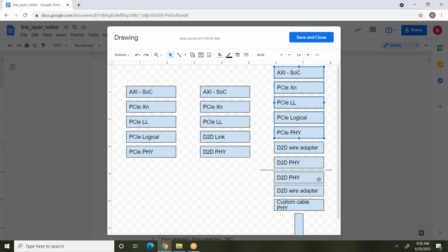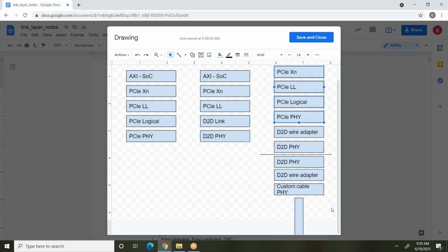Bapi, I have a couple of questions. When you have a PCIe PHY talking to the D2D PHY, the protocol itself is different, is it right? No, these are just bits. As far as this die-to-die PHY is concerned, it doesn't know whether it's carrying PCIe or AXI or anything. It's just seeing a bunch of streaming bits. It doesn't care. And because PCIe requires quite a bit of hand holding in terms of protocol, D2D PHY is just sending and receiving.